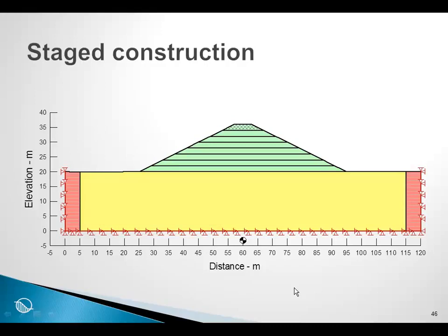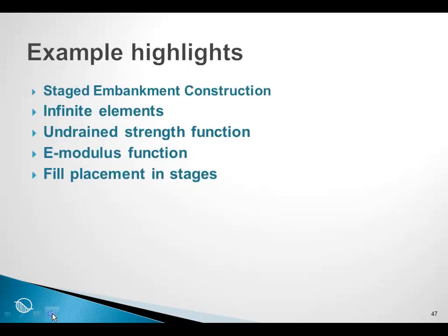This example is about showing how SIGMA/W can be used to simulate staged construction. In addition, we'll use this example to illustrate the use of infinite elements, and we are going to show with this example how to define undrained strengths that increase with depth and are defined as a function.